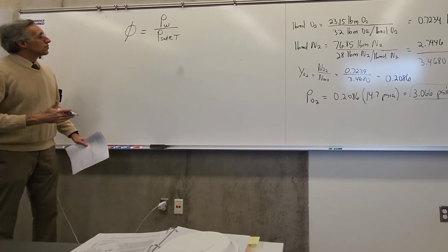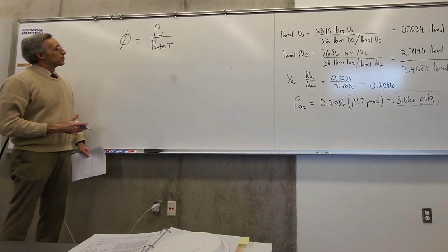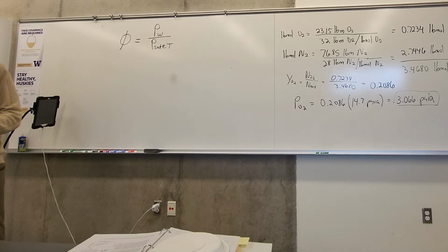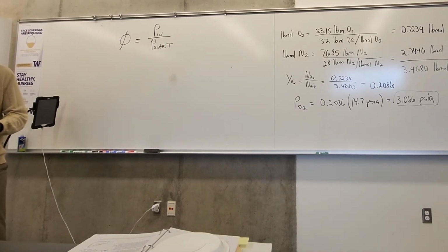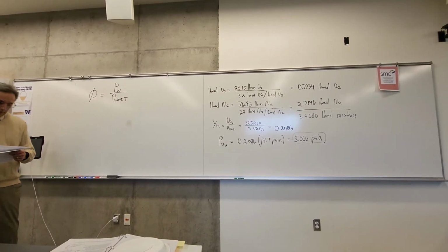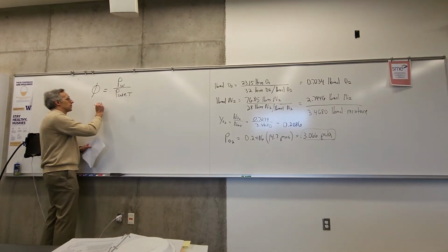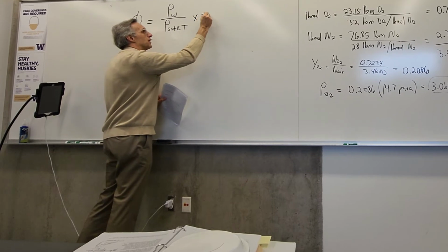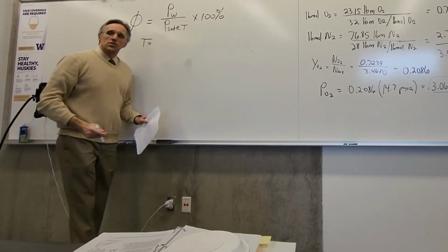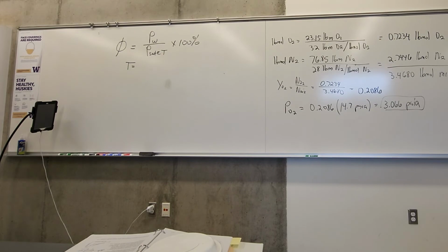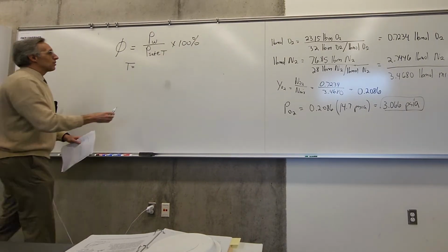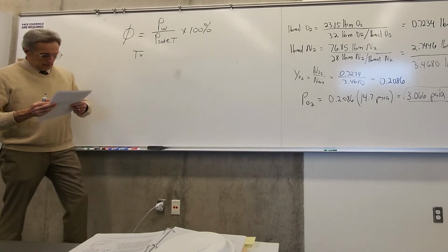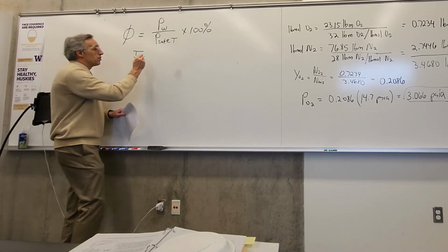So the partial pressure of the water vapor in the air to the saturation pressure at the given temperature. And in this problem, the temperature is 104 degrees. Technically we talk about relative humidity in percentage terms, that's the conventional way, but in calculations we always use it as a decimal. Okay, so the temperature is 104 degrees.